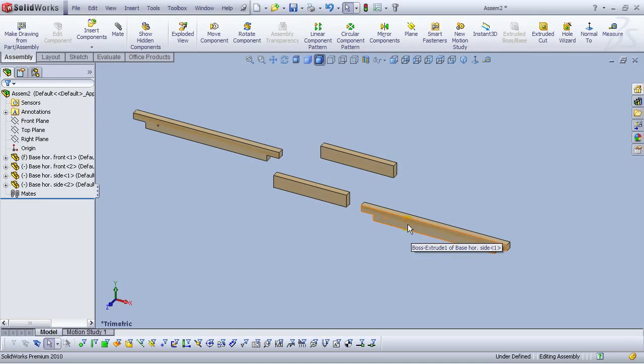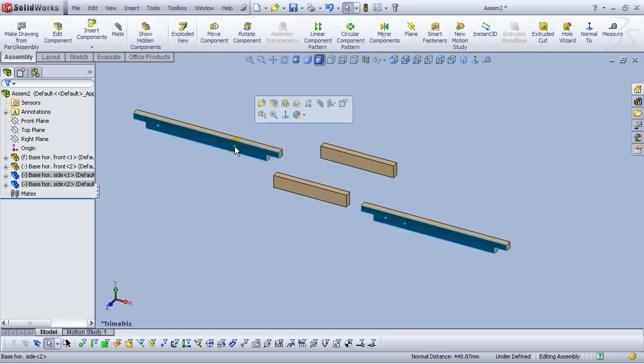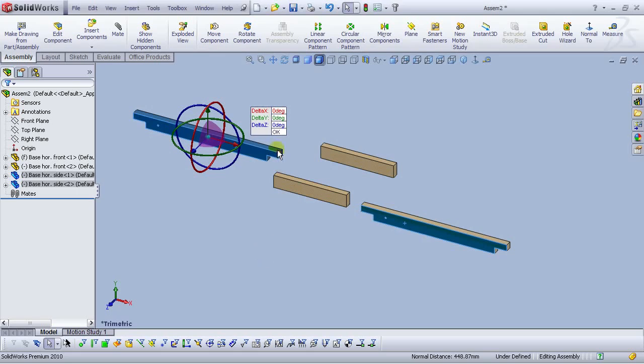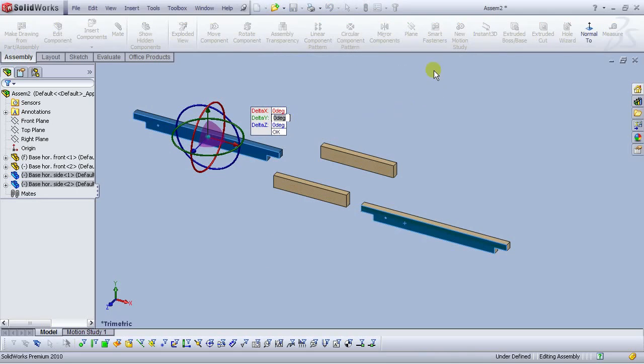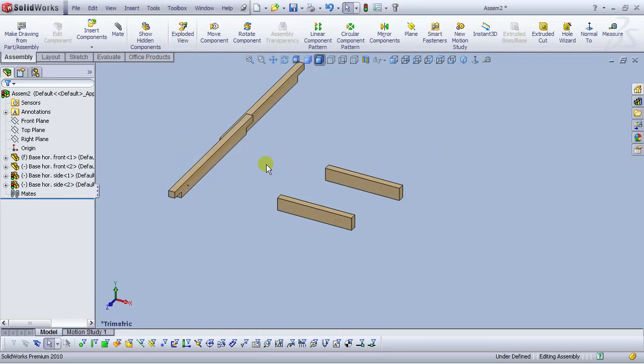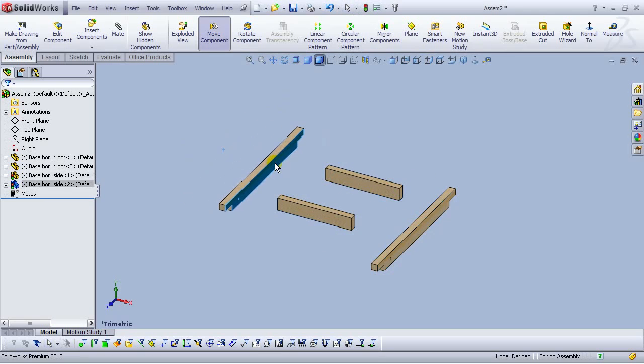Now let's rotate this one. Select this face, hold Ctrl and select this face here, and now click on the right mouse button and move it right. Let's rotate by y-axis 90 degrees. Select enter. Looks okay. Let's move it right about here, holding the left mouse key.